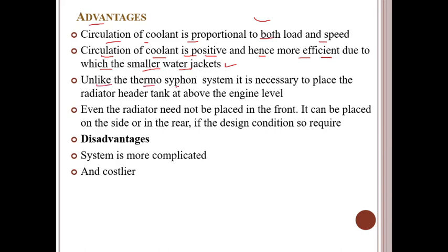Unlike the thermosiphon system, it is not necessary to place the radiator header tank above the engine level, and the radiator need not be placed in front. It can be placed on the side or near the rear if the design so requires. And what are the disadvantages? The system is more complicated and costlier. These are the disadvantages of this forced circulation cooling system, the pump circulation system.